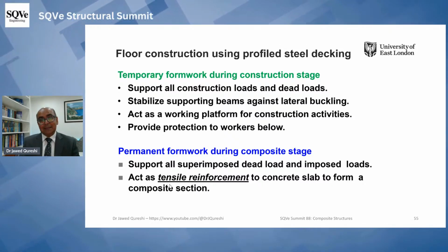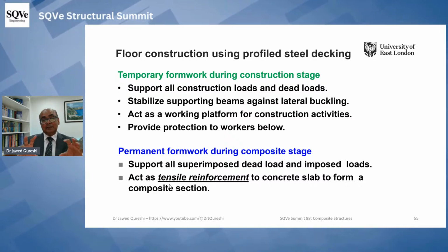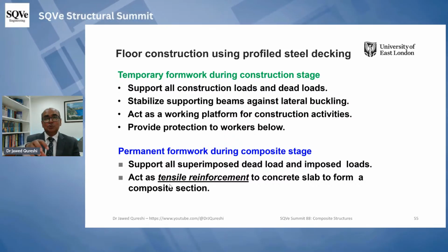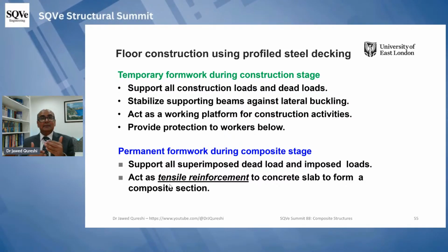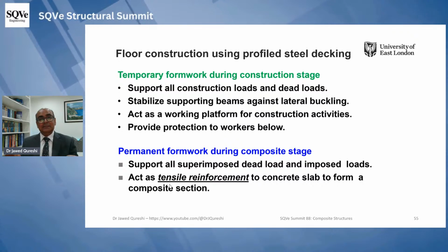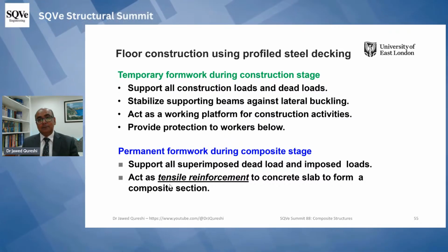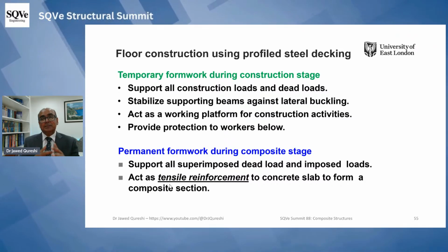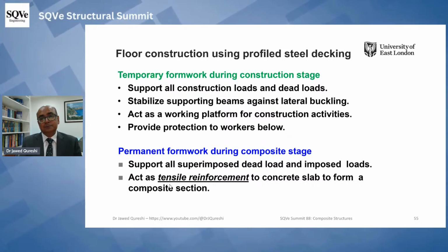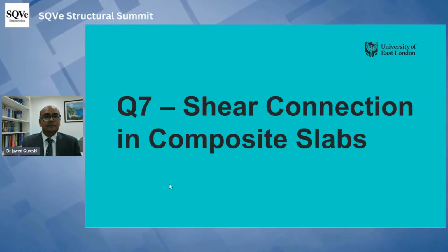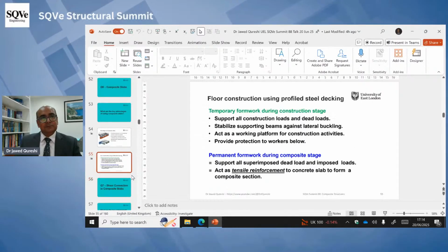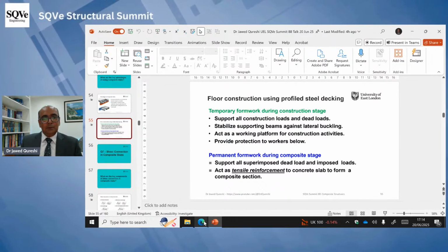And the beauty is that nowadays you can use these demountable shear studs, which can be bolted to the flange of the beam. And as a result, you can remove these slabs anytime you want. So the shear studs don't have to be welded, but still we need a little bit more information about it. Research is undergoing, and they are not still included in design codes. Okay, can we move to next question?